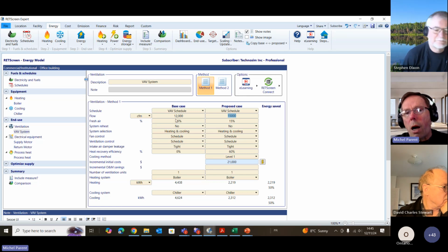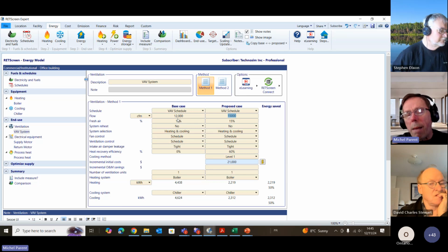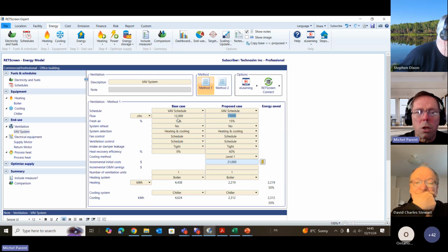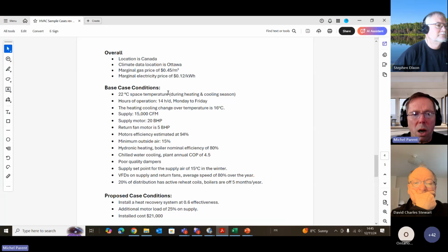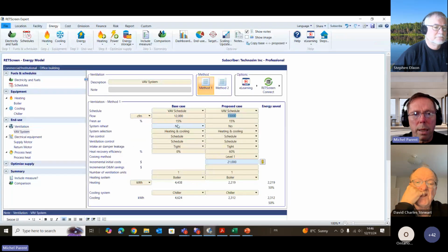And if your outside air is always at the same damper position, you probably don't modulate your damper position based on the VFD speed, which is extremely rare. So you could enter 15%. Let's check if there are separate exhausts on this system. There is no separate exhaust, so you can enter that 15% directly in here.